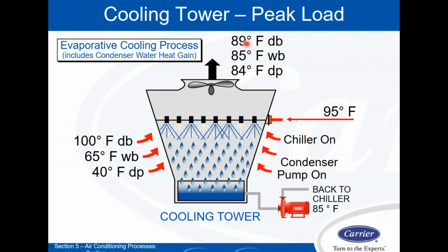But it's going to cool that down to 89 degrees. In that process, my water is going to be cooled because I'm taking the latent energy, the latent heat out of that 95 and sending it out. And I am thereby cooling the water down to 85 to send it back.